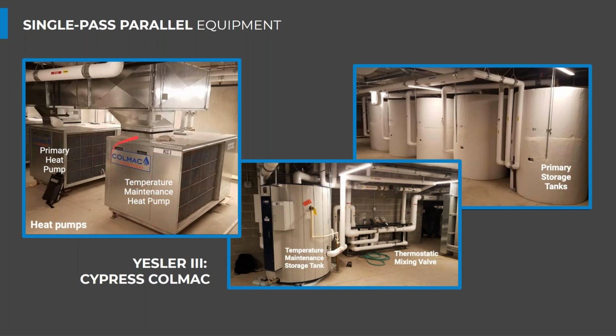We're just trying to put 10 degrees into that water through each cycle of that heat pump water heater. So although you might think that a multi-pass heat pump and a single pass look different, they often don't. It's really just some internal control settings and sizing of those components in that cabinet we see there.